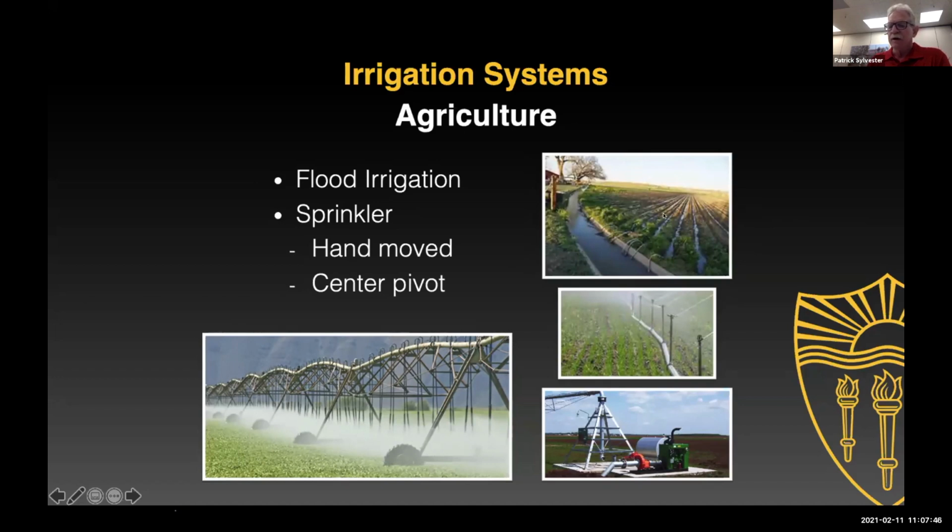So again, flood irrigation, the sprinklers, the center pivot, whatever it is, for agricultural, you're likely going to be seeing situations where chemicals are added or can be added. If you're the cross connection control specialist and they can be added, that's going to be your judgment call. What do you do? The potential is there. So do you require the backflow preventer? Maybe they're not adding it today, but maybe they decide to add it next week, but you've got a backflow preventer on there.